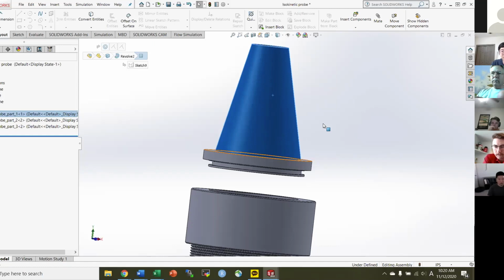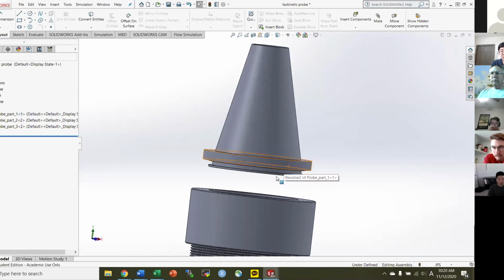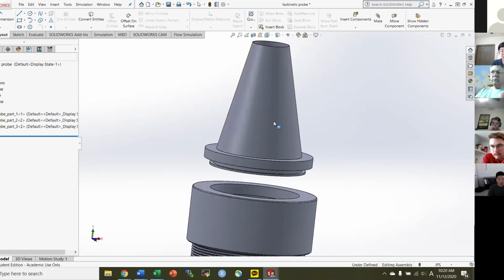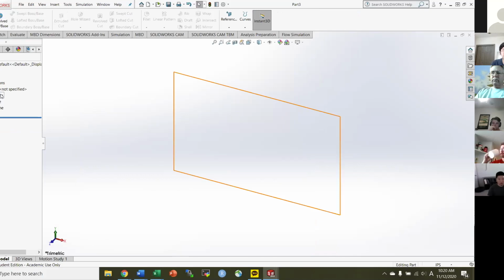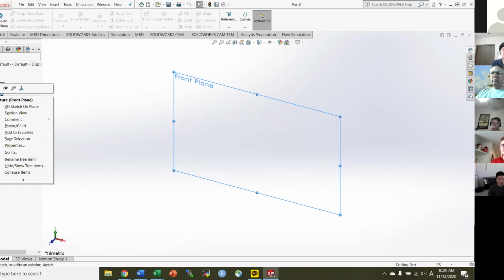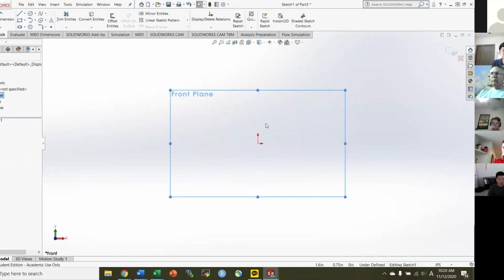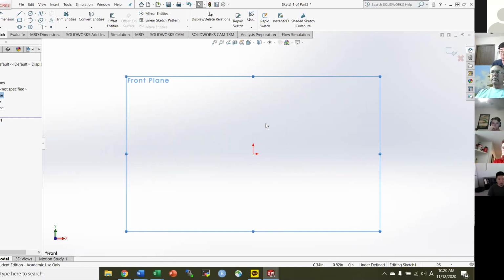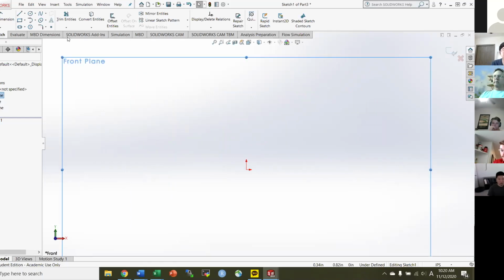So you can also go to a cylinder mode and then extrude all the way and then cut it down. But it is a bit more complicated because it's a cone shape, not a cylinder anymore. So it'll be more difficult to cut it. So I'll show you another option to create this kind of shape, even with a cylinder also. So instead of going to the top plane now, you'll go to the front plane and you'll click on sketch.